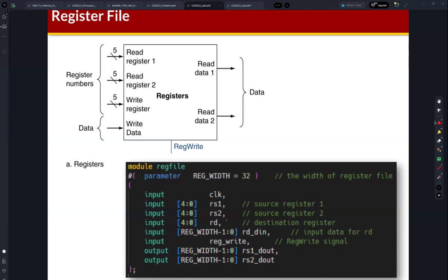But the concept is a little bit different. It is because the C programming language is not designed for hardware design, right? So it means this C code cannot support some features of SystemVerilog. So this is the disadvantage. But if we can convert the SystemVerilog module to this C module using Verilator, then we can perform the SystemVerilog simulation very quickly.